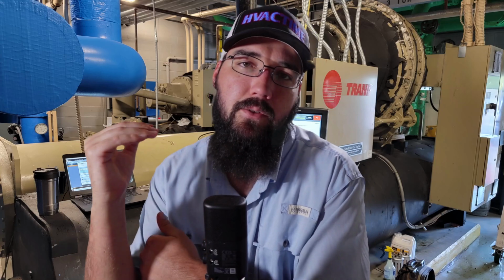Okay. So a big part of every system is going to struggle with, a big part of its system is being able to get the oil back. And this is specifically an issue with shell and tube flooded styles of evaporators or hybrid falling film. And I'll show those in a minute.